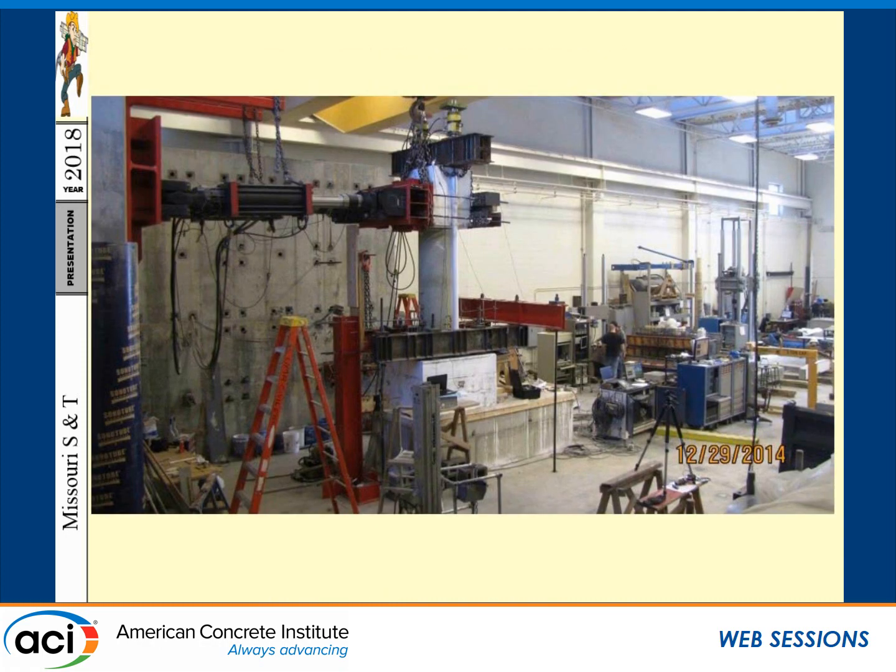So here is the test setup in Missouri S&T. We fix the column to the lab strong floor over here. This is the footing. And then we have two actuators over here. The actuators go back and forth to mimic a cyclic load. This is the axial load. We have load cells and hydraulic jacks over here to keep the axial load constant during testing.